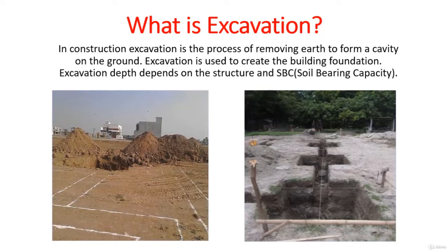But even before this, we have a basic step of marking the plots before excavation. This process of plot marking involves marking the actual measures of footing on the site with the help of lime or chalk powder. So by marking the foundation area of the building with chalk powder, we make it clear as to which areas are to be excavated.